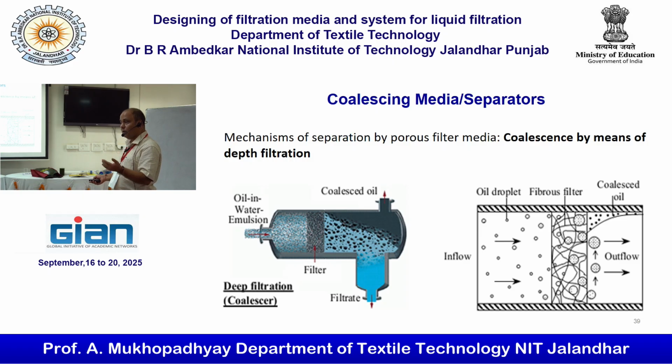This is different from the other techniques I have referred to. This is another technique where we separate the oil, but here based on a surface filter. The earlier one was depth filtration, where it moves to the other side. Here it is based on surface filtration because you want it to be arrested on the surface. Whenever it is arrested on the surface, it becomes bigger and tends to float, and the pump will be on this side, on the upstream side.